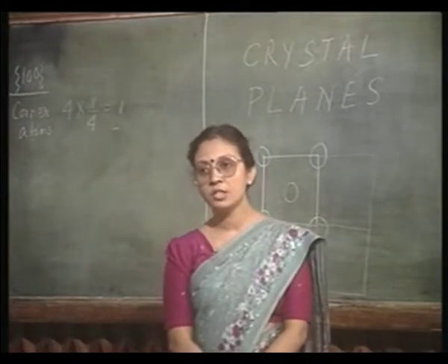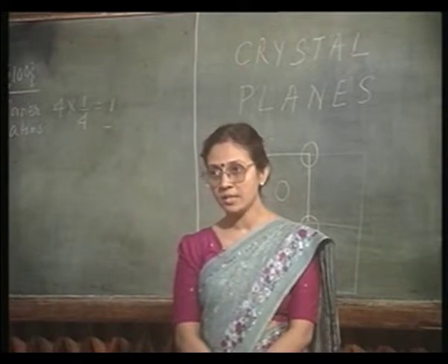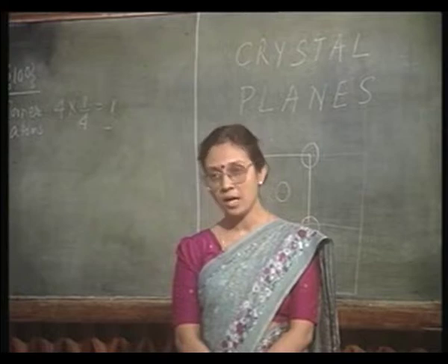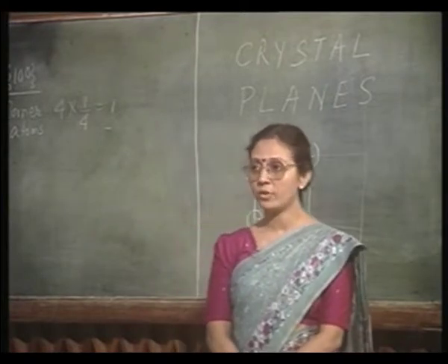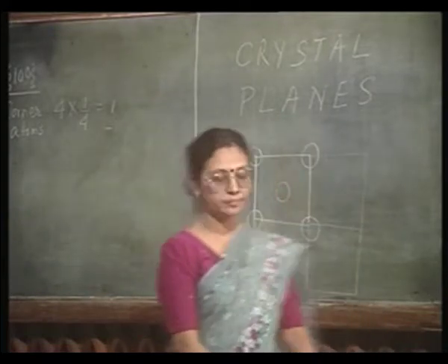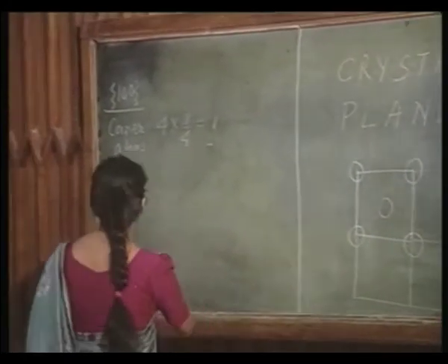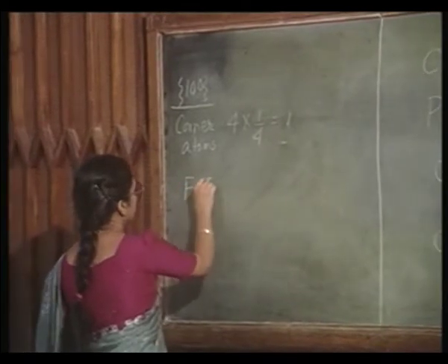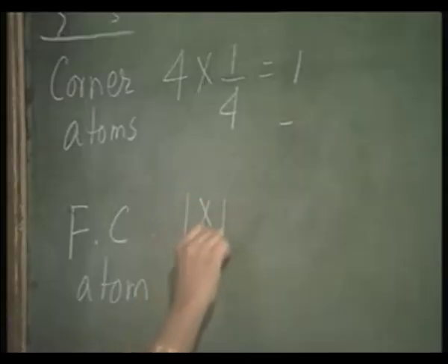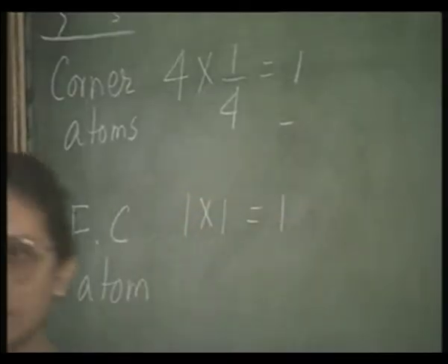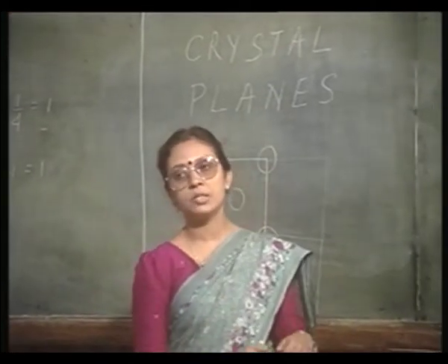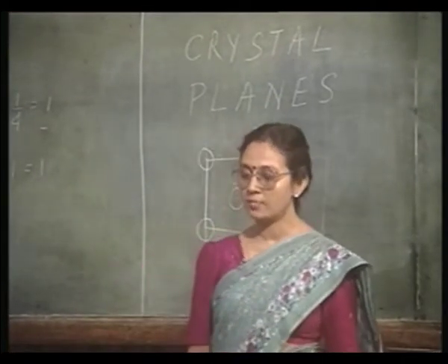This is uniquely contained in one 1 0 0 plane. It cannot be shared by other 1 0 0 planes. Therefore, its contribution to the 1 0 0 plane is unity, it is 1. So, in other words, the total contribution of the atoms to this 1 0 0 plane is simply 2.